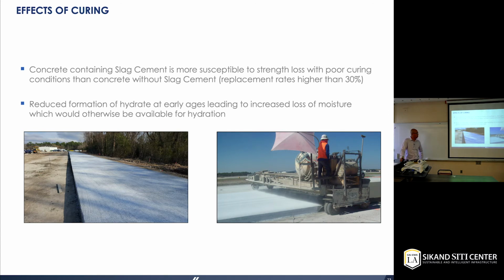One thing I have to mention to all the contractors is that curing is very important for concrete mixes with a high percentage of slag, because not only hydraulic reactivity but also pozzolanic reactivity takes place in your concrete mix. So it takes longer compared to conventional concrete.